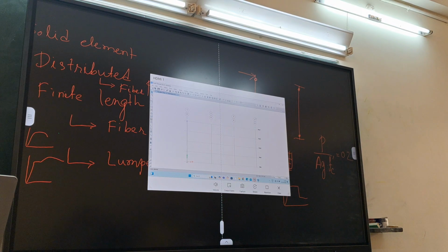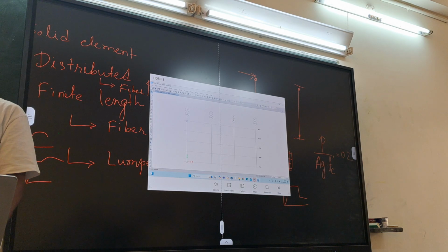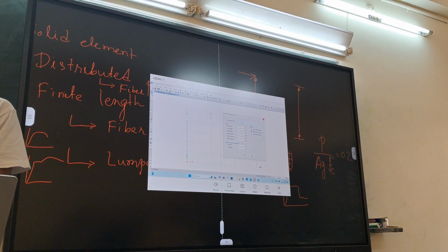Okay, so the calculated load, meaning the actual load, is coming to be 3840 kilonewton. Now this you can apply as a joint load. So you can click on this node, then go to assign, then go to joint load, then force. Here you can select under which category you want to apply. Since live load is already defined by default here, I am applying this one, but if you want to make it any other category, you can define it first. And what will be the direction?